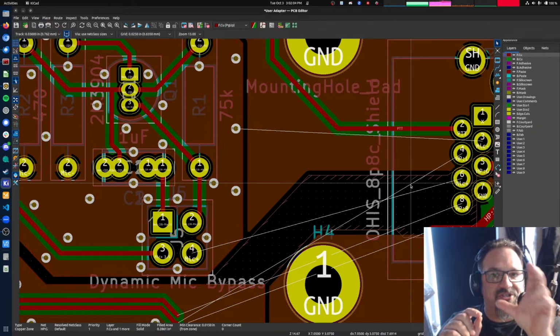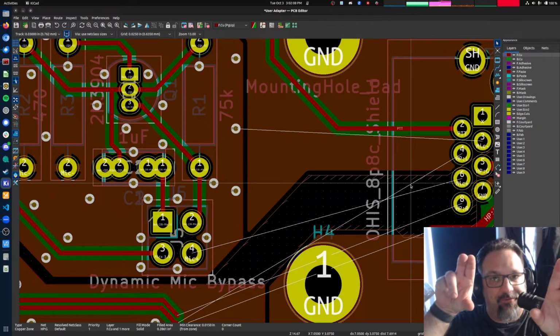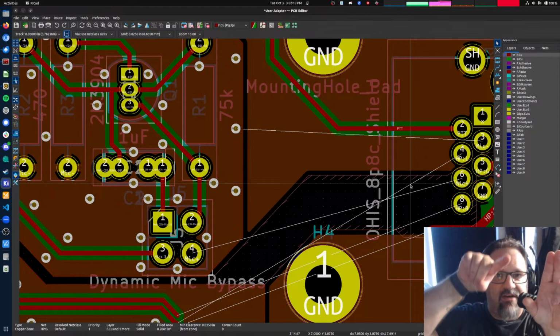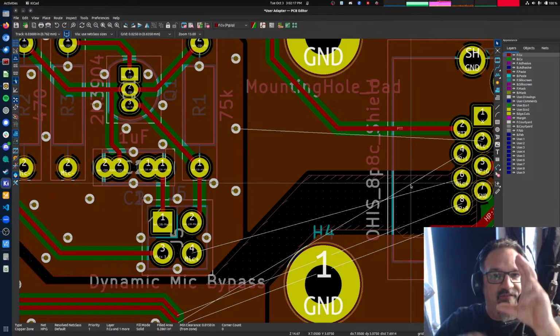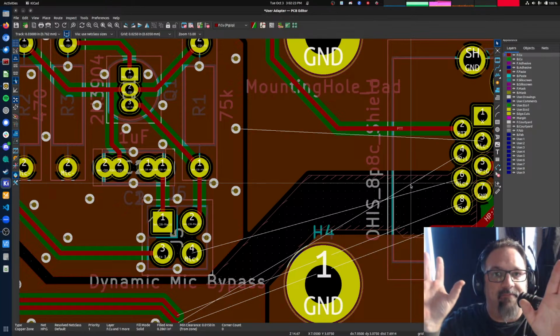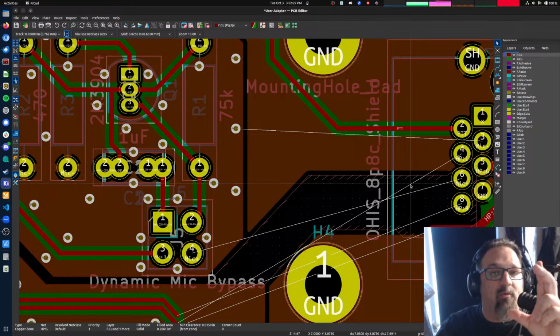Now, if you're sharing the return currents between your headphones and your microphone, that means your headphone current is coming in the same ground that your microphone is using. If that ground is 0 ohms, then whatever current goes through results in a 0 volt drop. But if that ground is, say, 0.1 ohms, that's pretty high.